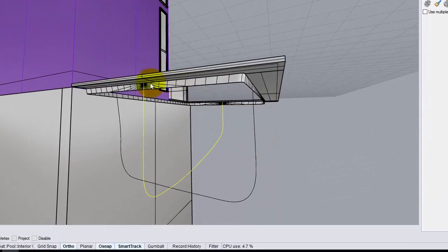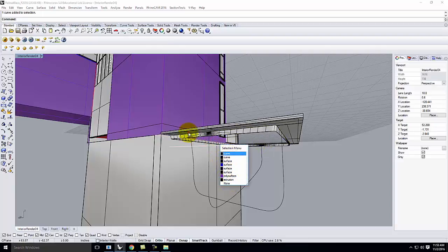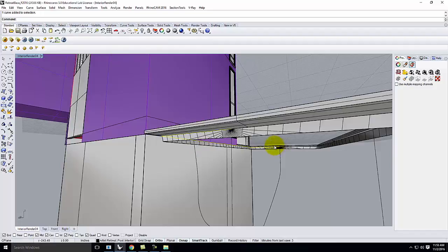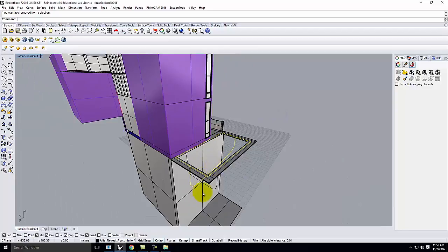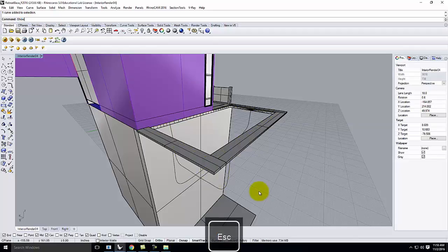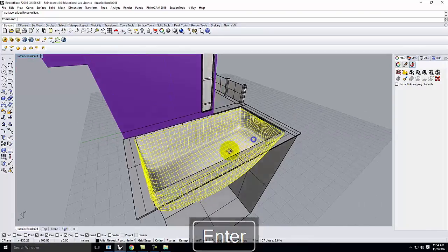Then I did a curve that goes right along here at the top, and this one goes over straight to 90, over straight to 90, and back over to here. I have the opposite curve on this side, if I can select it. There it is, right there. So that curve plus this curve plus that curve are three curves going in the same direction. This curve is the curve that goes in the opposite direction. And so I was able to create a curve network that makes that shape, which is essentially the pool shape.